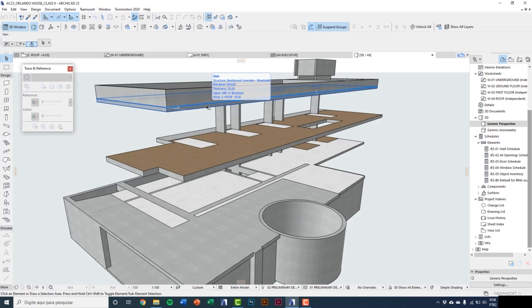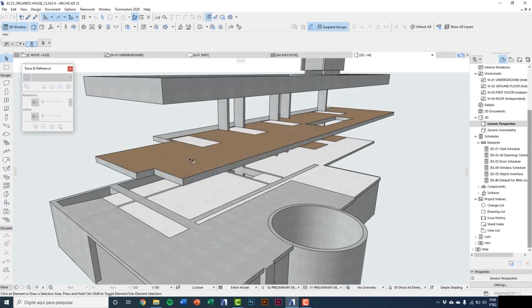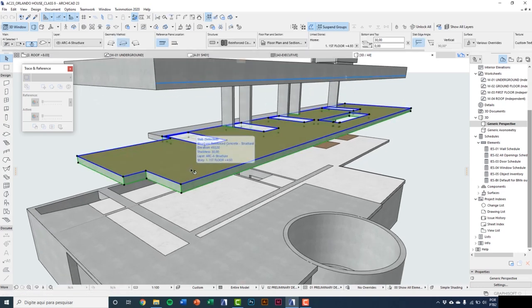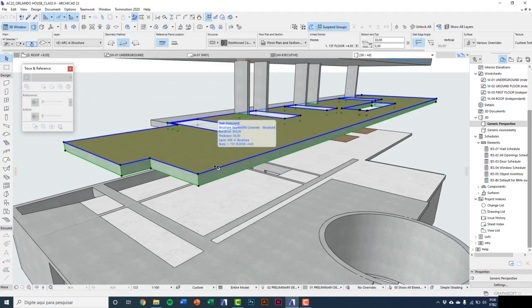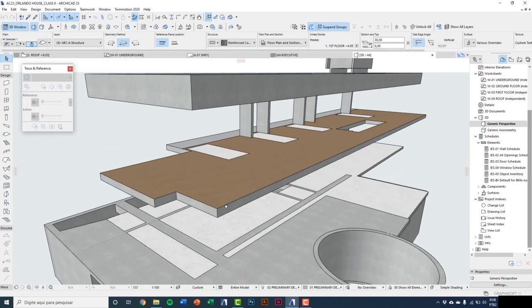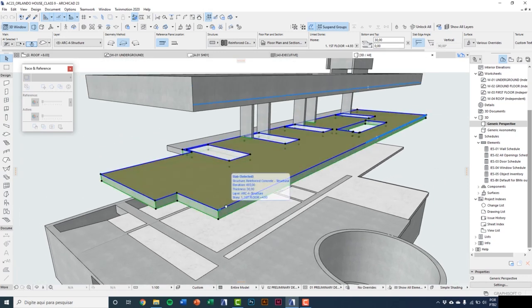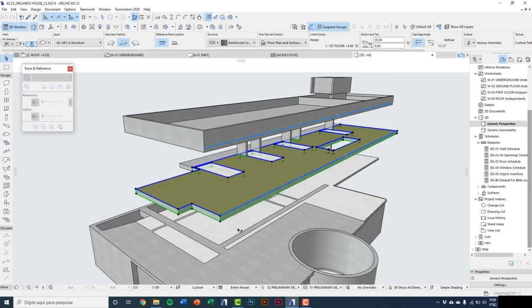This house has a structure composed of pre-stressed concrete. And this is the reason why I have a 30 centimeters slab without beams. That allows big gaps between columns, and still we're gonna do steel and concrete columns to complete the structure. But for now, let's start making a ramp to access garage. Go into underground floor.